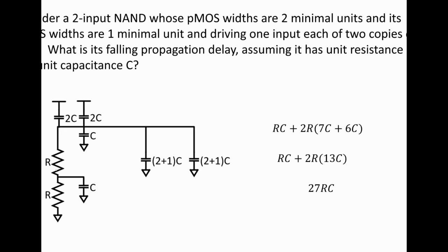If each transistor has 1 C in each of its diffusion areas, then aren't there 2 diffusion areas that are linking these 2 guys? There's 2 transistors. You're basically connecting the source of one to the drain of the other, right? That diffusion area in between the 2 NMOSs should give you 2 units of capacitance, should it not?